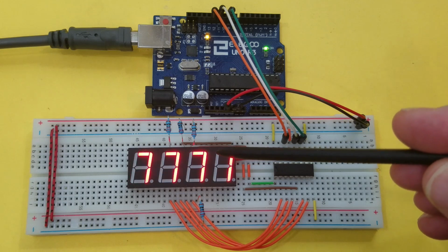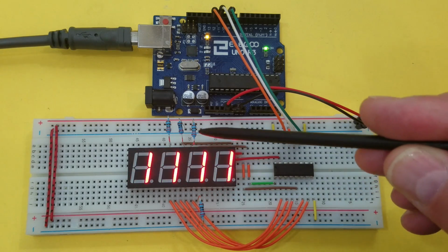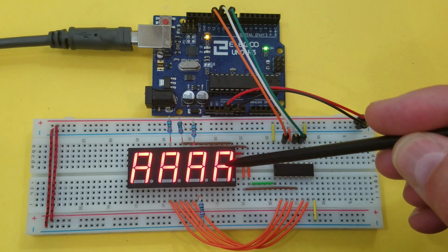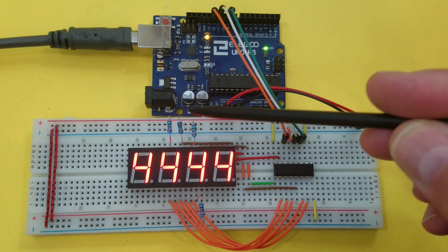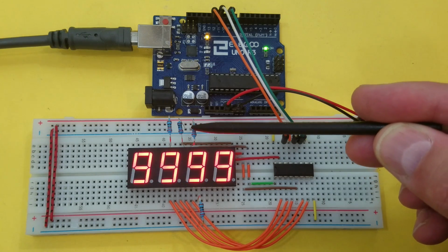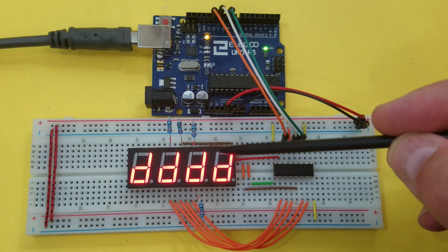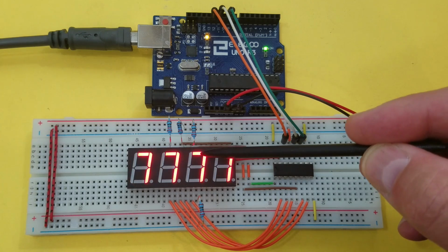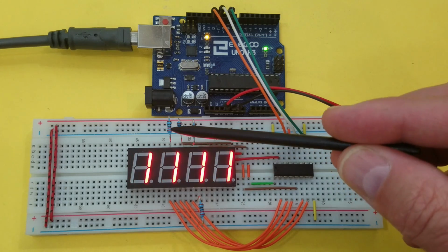What's important is that the resistors here that are connecting the common cathodes for each of the digits are now connected to ground. What we need to do is control each of these digits' common cathodes so that we can control each digit independently. That way, we show one digit value, then switch on another digit and show a value, then the third and the fourth.